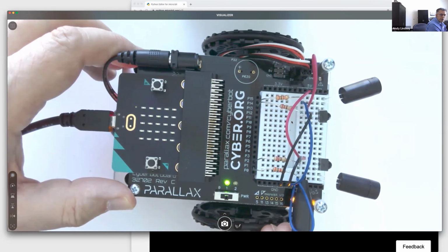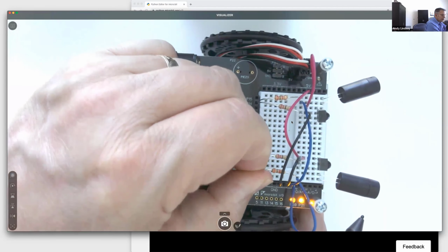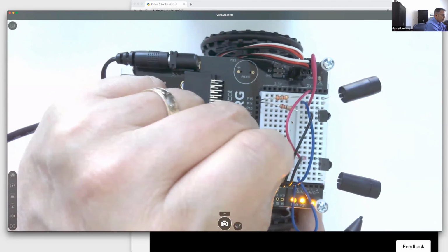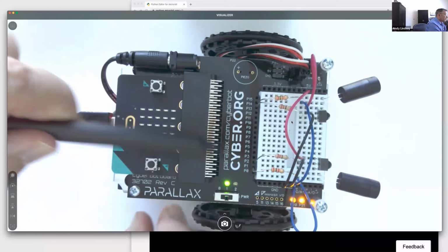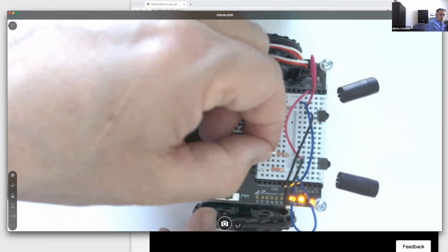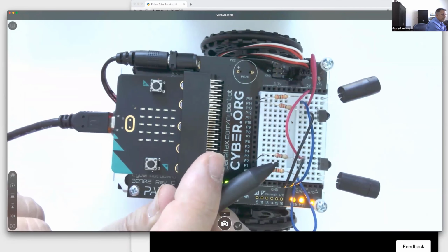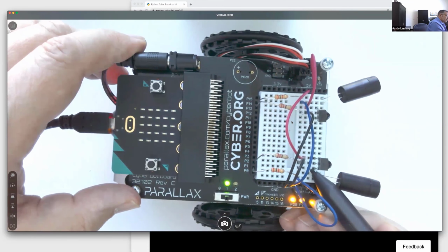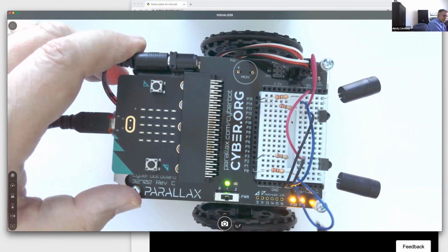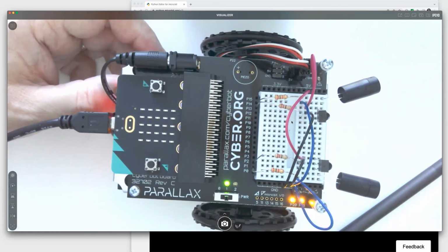So 1, 2. Then you'll have verified, and then also pull up a little bit and push in a little bit for both ends of that resistor. Then repeat the same thing for the P2 resistor. Make sure that it's well connected to P2, that it's red, red, brown, and that it's going into the third row up. This is where the red, red, brown goes, the third row up. I got a frowny face when I put this in.